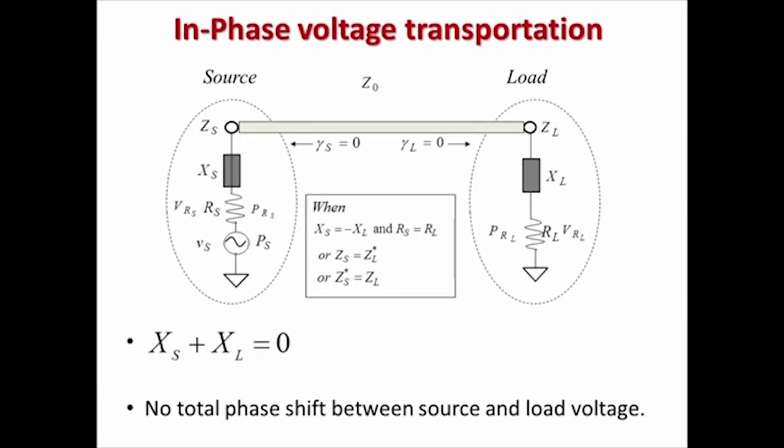One of the techniques is this: you find out when you are getting half of the power, because you know the source power. Let us say the source power is 1 watt. The moment you see that across RS you are getting half of that power, that means half a watt, you know that you have got a match, a conjugate match between source and load.